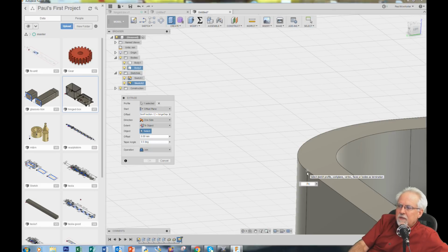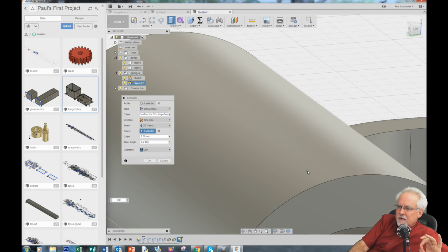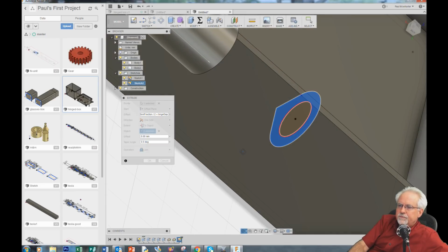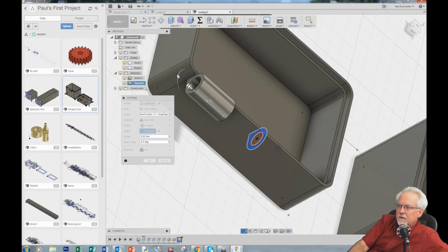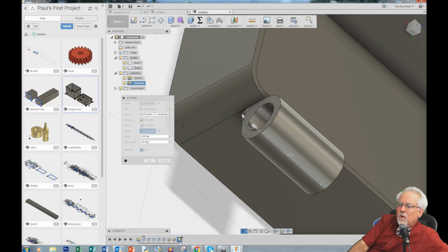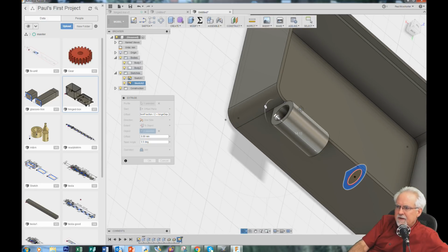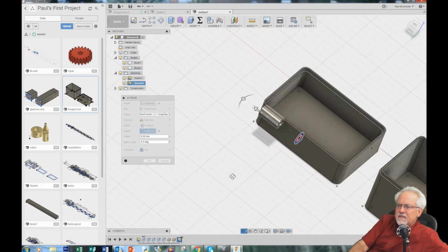And I'm not clicking randomly. You see how it recognizes it? It lights up a point there. That's that intersection. Click. I hope that worked. That should always go to that intersection. Okay, yes. Look. Why did we do it that way? As I change the dimensions now, this edge is always going to be pinned to that corner. So if I change the rounding, this is going to adjust to always come out to the edge of the corner. So if I change the corner, this isn't going to end up sticking out in air. It's always going to align there. This is design intent. This is thinking about things.